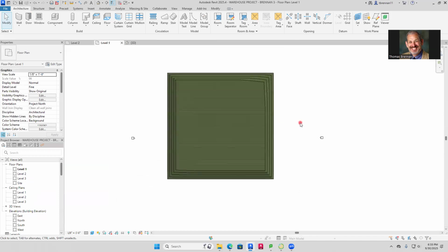We're going to make a slab. Now, this is where this gets really good. We're going to make a slab, and then we're going to excavate the topography so the slab actually sinks into it. This is kind of cool here. All right, so what you're going to do now, you're going to go over here and put in a floor. So go up here to floor.